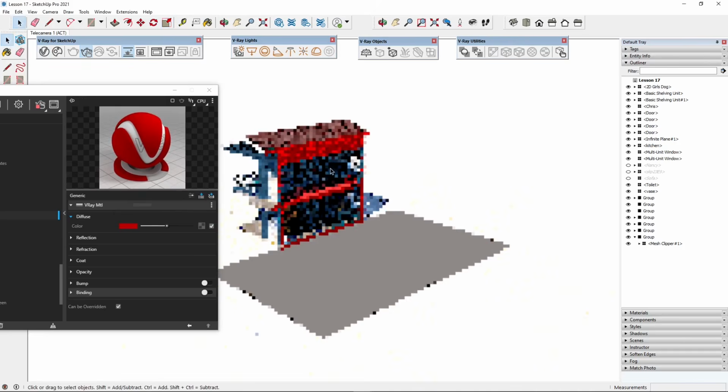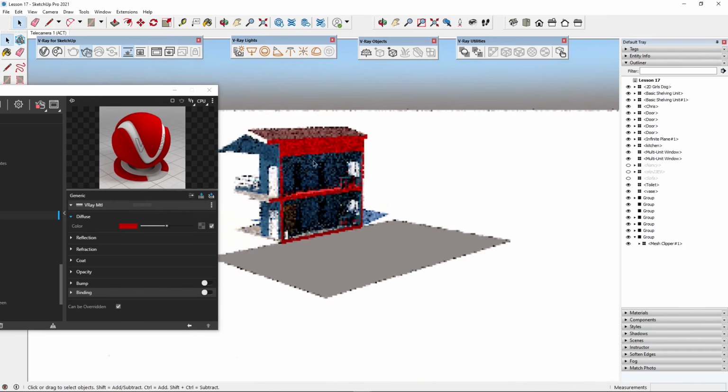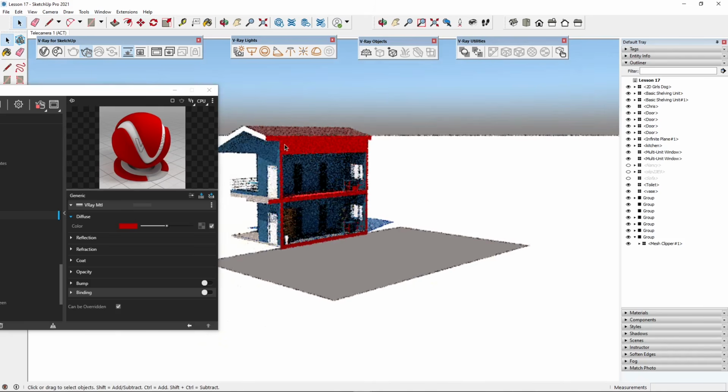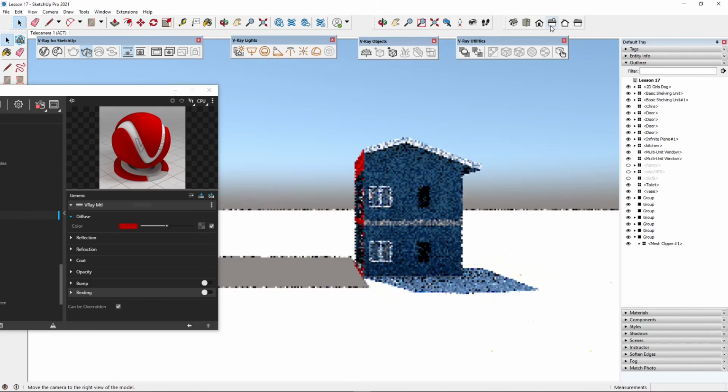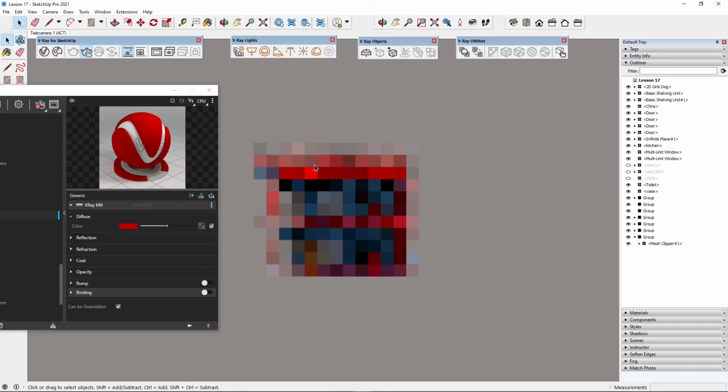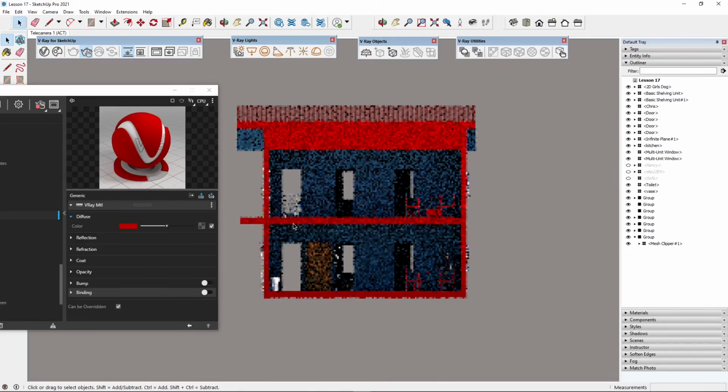So now this depends on how you created your 3D model. You can see here probably I would have some empty part, but in this case it's showing this as an entire block. But you can see here this is a nice section. You can also use the views here in SketchUp. This is a front view, and we can go to camera and go to parallel projection if you want 2D like a CAD drawing.